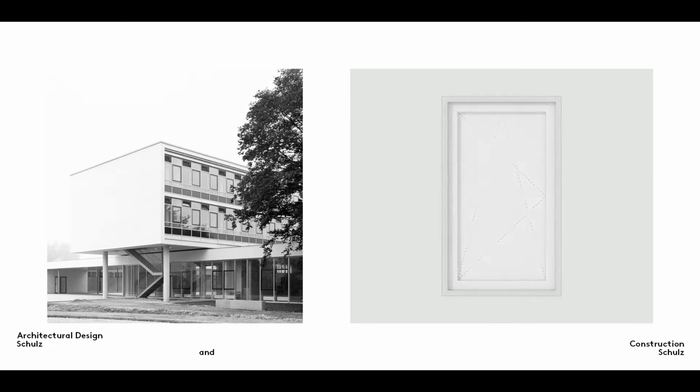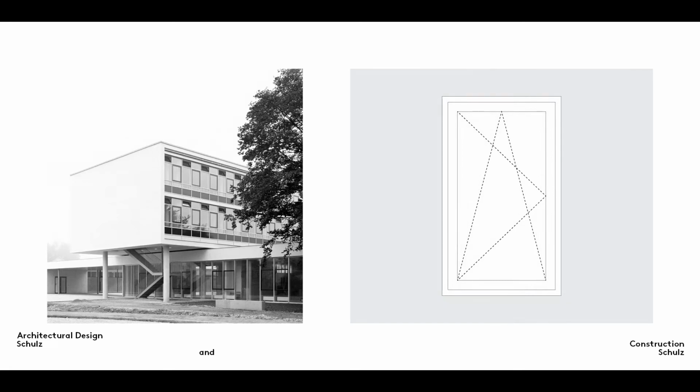Here, you can see the most common type of window fitted in Germany. It can be opened in two different directions, by tilting and by turning, and is known as a tilt and turn window. In elevation drawings, this type of window is represented by two isosceles triangles with their bases running along the axis of rotation and their points indicating the center of the opening side.